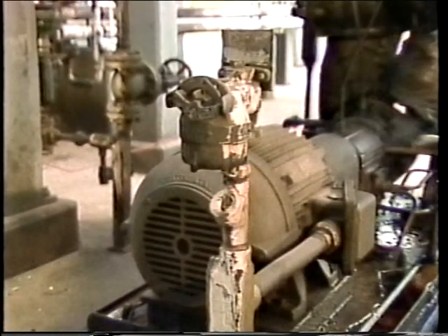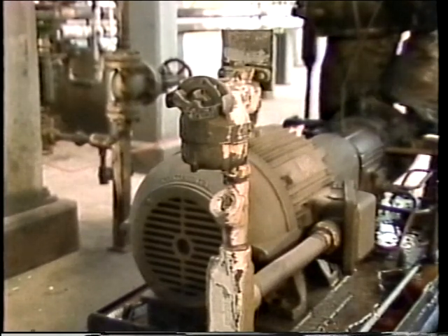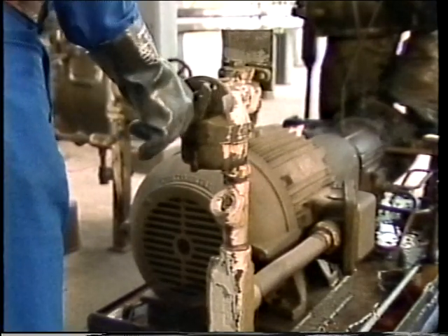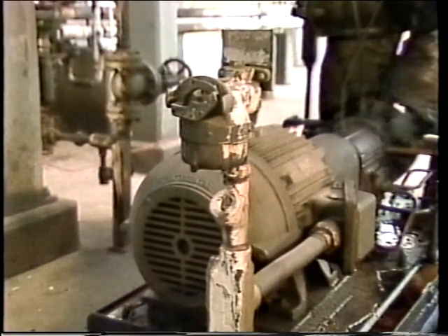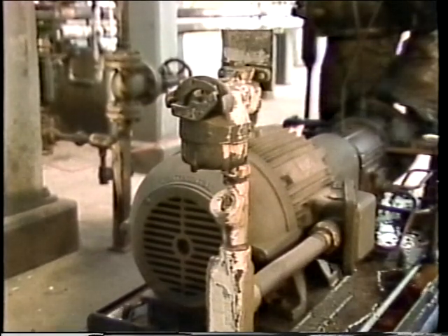Since baseline data is so important, it is critical that the operating conditions of the machinery are the same each time vibration testing is performed. If conditions are not matched correctly, the actual vibration of the machine could be masked or exaggerated, and problems could go undetected. There are many parameters that should be checked to ensure that conditions are matched as closely as possible. For example, a machine should be started in accordance with the manufacturer's guidelines or company procedures, and given sufficient time to warm up before the data is collected. That way, the machine should be operating at the proper speed and temperature.